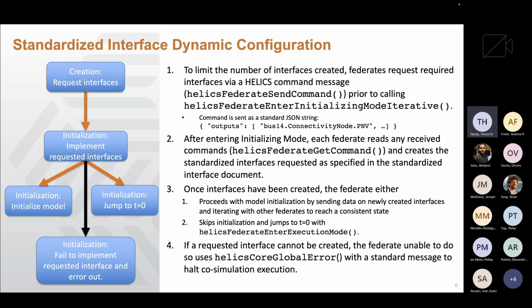Yeah, generally that's the idea. For the specific case you brought up, and this is again kind of a gap in the standard, like a T&D power flow, there shouldn't be a need to do dynamic configuration. Everybody should know where the point of common coupling is. That should all have been able to be defined ahead of time. The example maybe is in a voltage regulation use case, what voltages those controllers need is likely to be not standardizable at all.